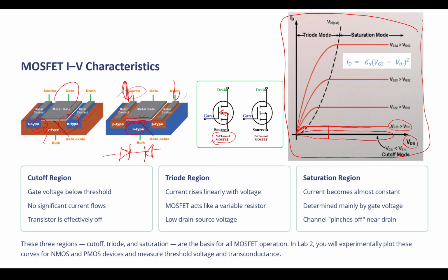Still, I wanted to again remind you of a concept that we learned about the diode. Remember when we wanted to turn the diode on, basically meaning we enter the forward bias, we had a threshold. It was not like any value of positive voltage in a forward bias would give us the current. We need to exceed a certain amount so we are actually able to force the charges to jump from one semiconductor to another. Same concept goes here.